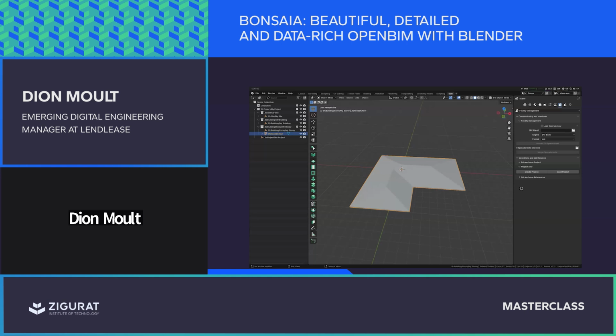But let's say you are progressing and you do know your individual objects and you're counting them. You then need to know what material they're made out of. So yes, IFC can obviously store the type of material. The example I showed you just then of that Revit model had very poor material data. I couldn't tell the steel grade of the steel. I couldn't tell, for example, the compressive strength of the concrete, or the density of rebar in that concrete. But IFC does have capabilities to do all this.